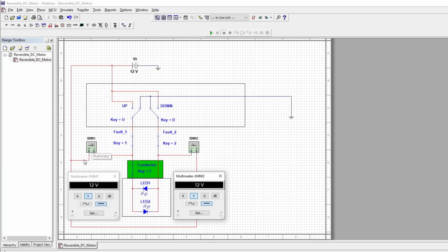So the positive of your voltmeter is connected to the positive of the battery, and you're probing the 2 input wires to the motor. And the reason why is when you're not touching these switches, look at where the lines go. They go straight to ground. And on this side here, straight to ground. This is the position of these switches when you're not touching them. So it makes sense if right at the motor, you test for a path to ground. And how you can test for a path to ground with a voltmeter is the positive lead of the voltmeter onto the positive of the battery, and then you just probe for that ground with the negative probe. And if you have that completed path, you'll get 12 volts. So let's turn this thing on and have a look here.